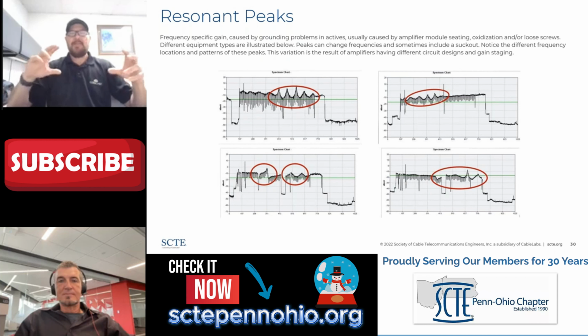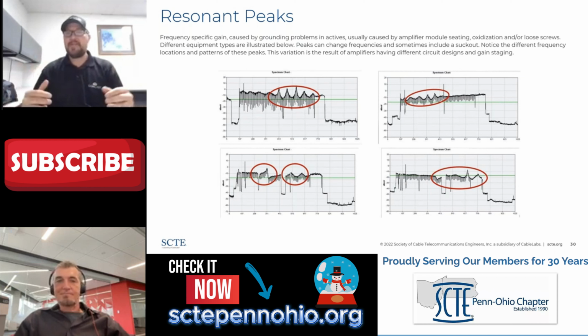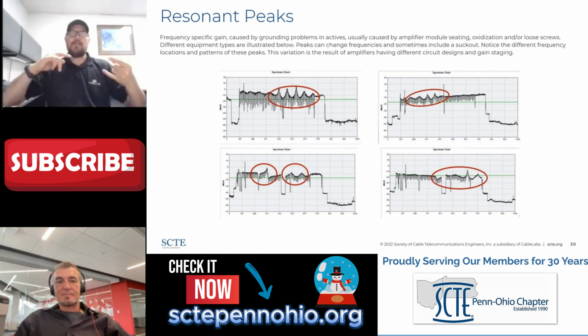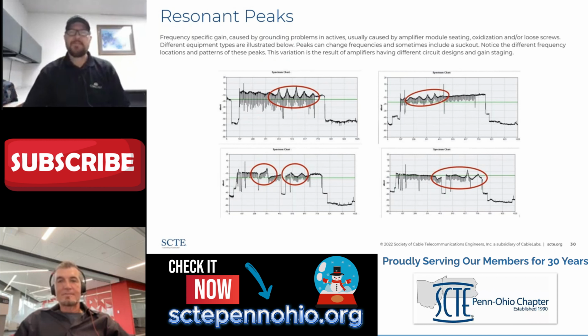And when that happens, if the module doesn't warp or twist exactly the same as the housing, maybe because the module retainer screws are loose, then we can create these peaks or these cavitations or oscillations inside the amplifier. So in a lot of cases, just opening the module or the housing and tightening the module retainer screws in the absence of corrosion will make this go away, because the module has torqued or warped inside of the housing.